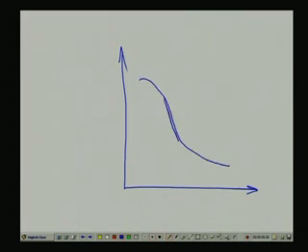So, I can approximate these positions and take this as a linear region. This actual operating point corresponds to 3 to 15 psi of pressure as a controlled output of the flapper nozzle system.